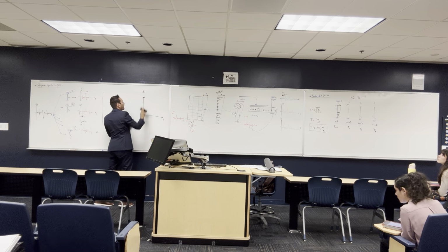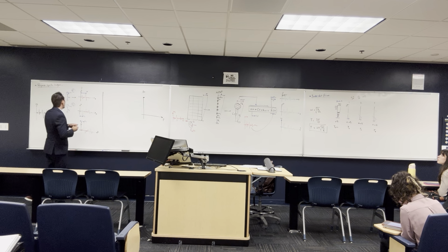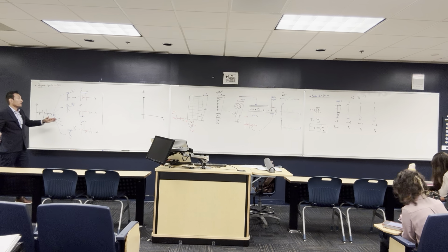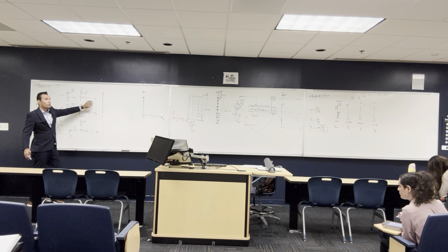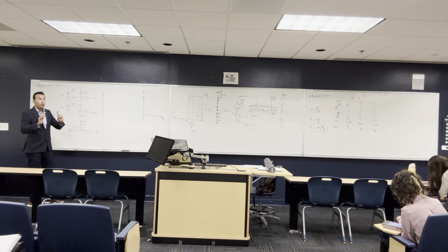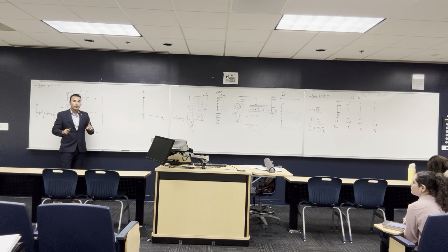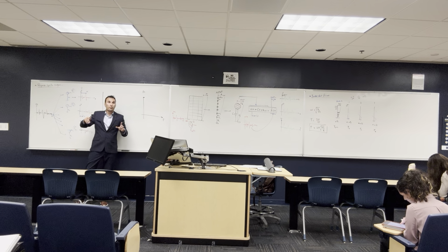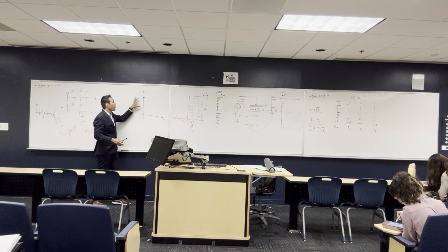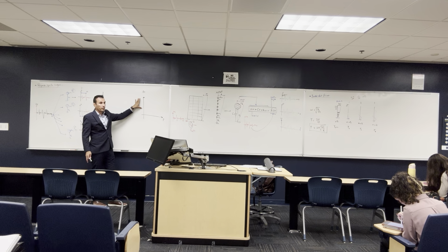Why do they call it the spectral acceleration, or why do they call this concept response spectrum? Because we pick a spectrum of buildings that have different characteristics. This spectrum includes tall, short, big, small buildings, and we are trying to find a relationship that can link all these buildings, a relationship between the characteristic of the buildings and the performance, or the acceleration, of the building.